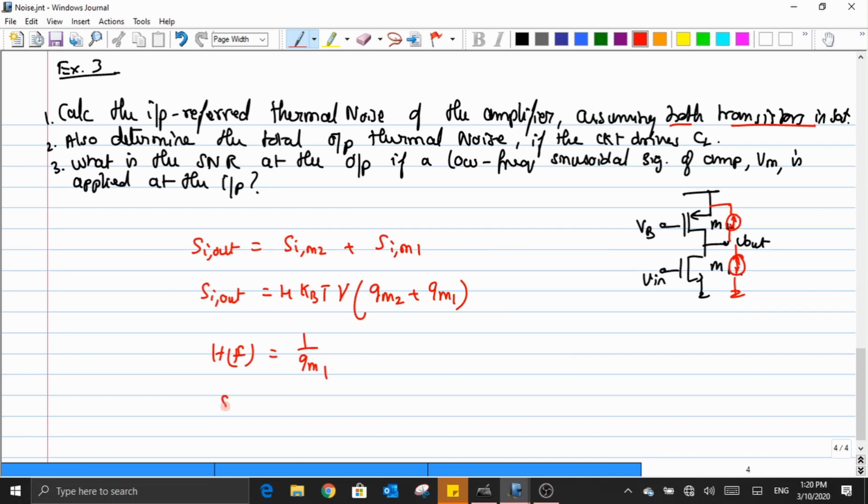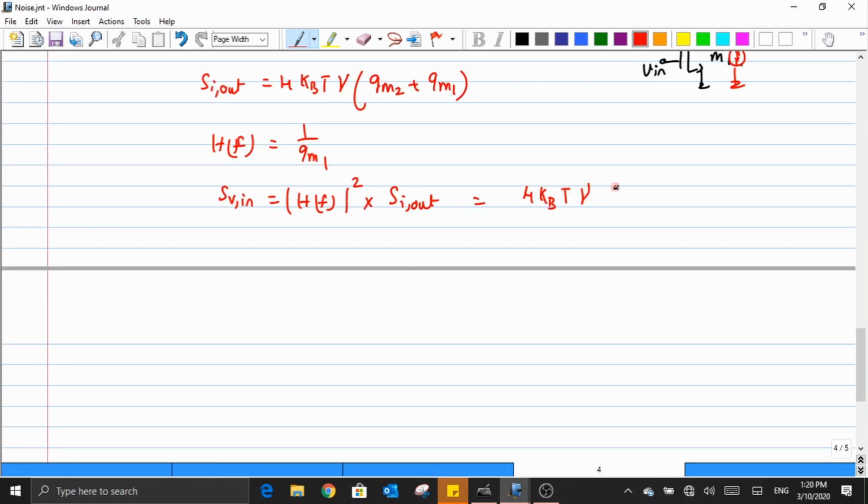So now we calculate the power spectral density at the input. Okay, so whatever we have got is just the power spectral density, but how will I convert it in terms of variance or in terms of power? We have to use the Wiener-Khinchin relation in order to convert this power spectral density into a variance term.